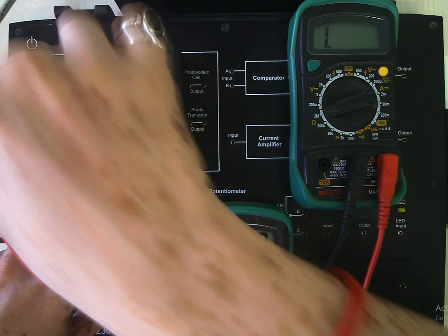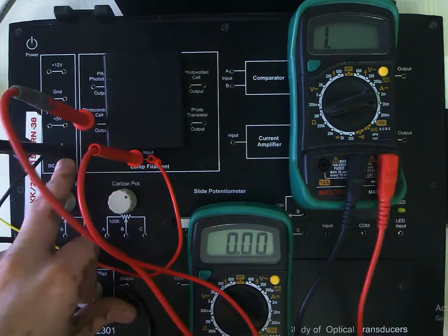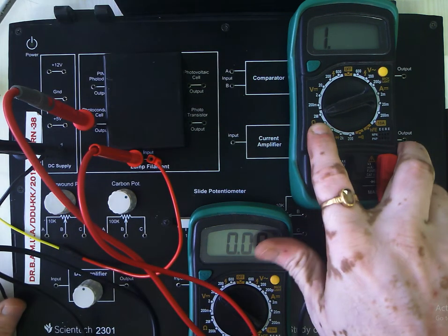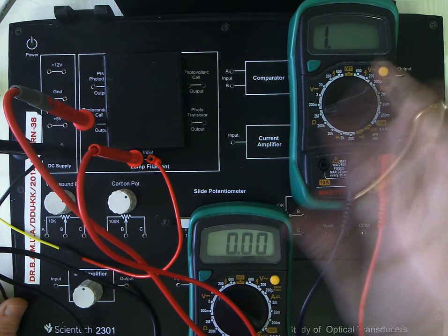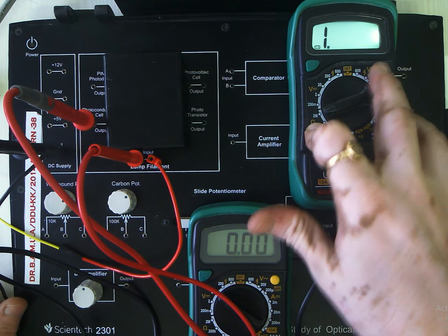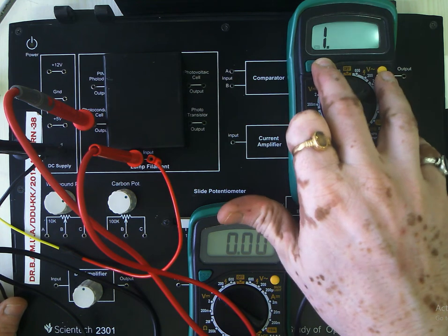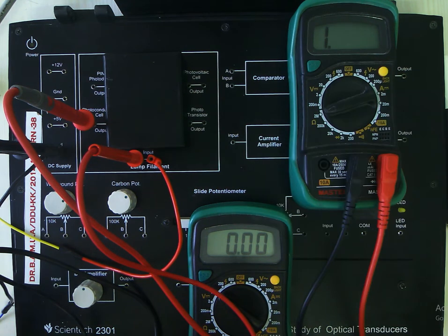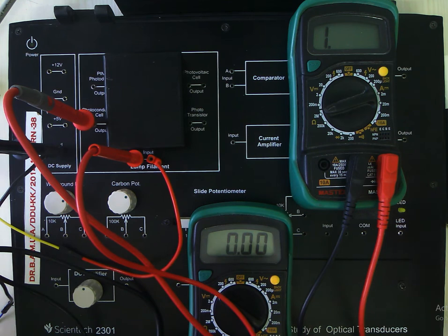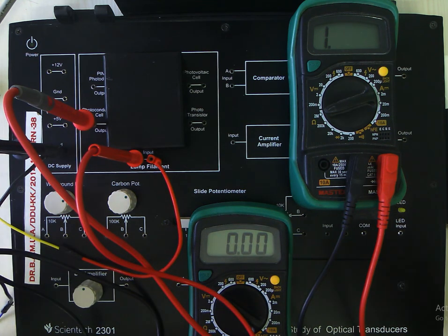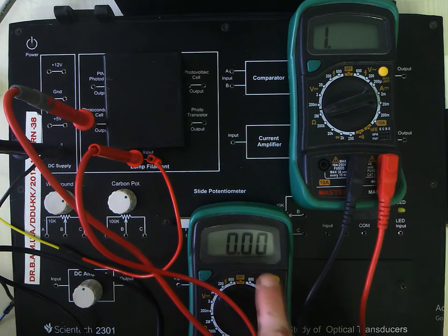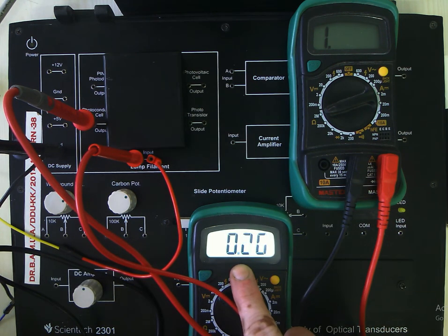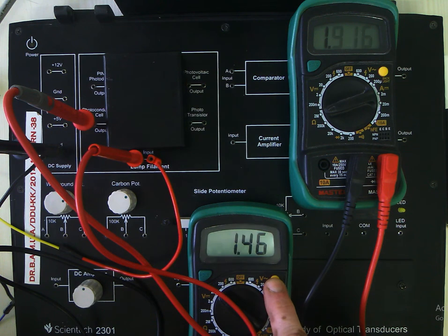So I will be connecting the photoconductive cell here. Now you can see the resistance range that I am using in this multimeter right now, it is 2 mega ohm, and you can see even that is unable to measure the resistance. So that means the resistance of the photoconductive cell in absence of any light is more than 2 mega ohm. It is very clear. So now I will be increasing the voltage. You can find here I am increasing the voltage, right? So I am gradually increasing the voltage.